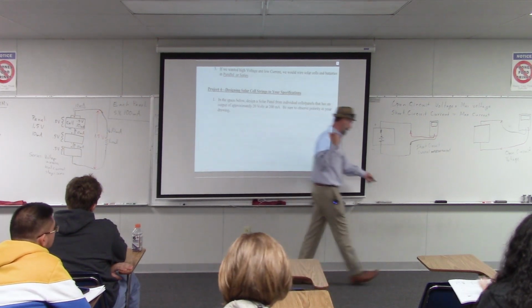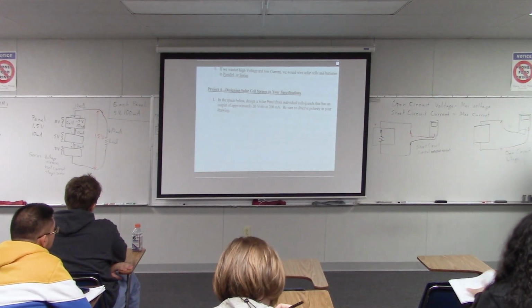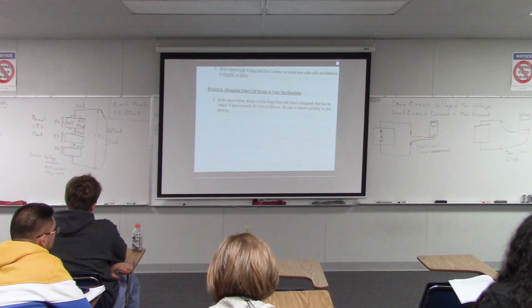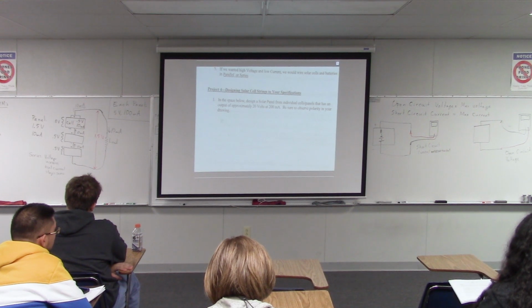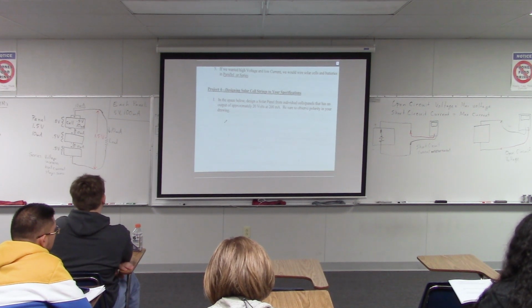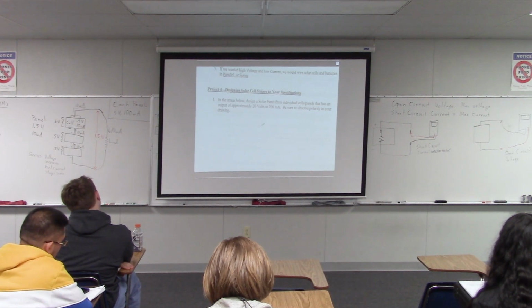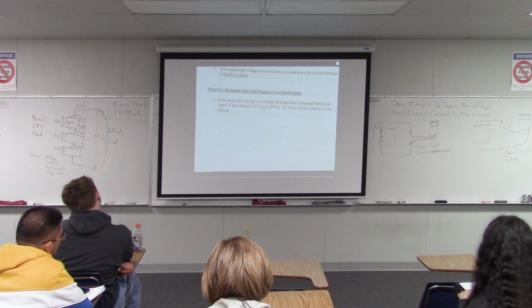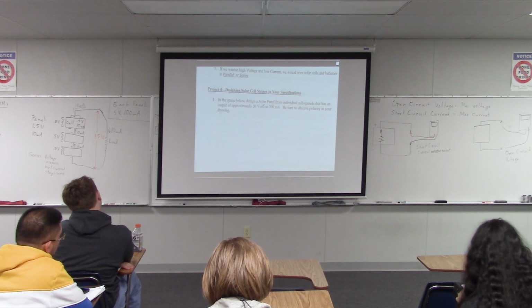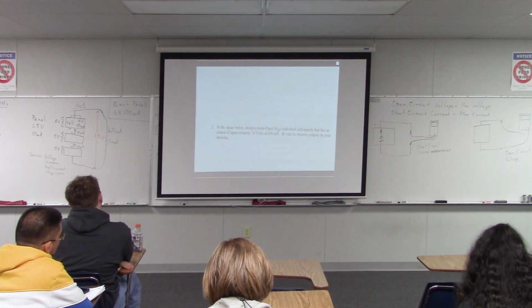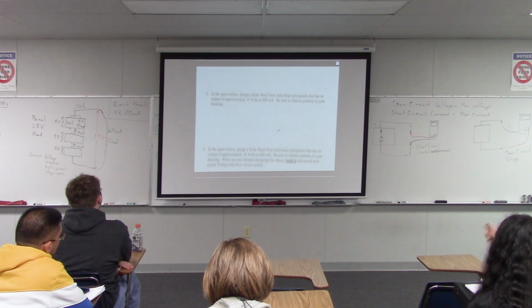And then I'd like you to draw the way that these designs would go, kind of the way that I drew the designs up on the board. So you can draw simplified panels that each have a positive and a negative terminal on it, and then show how you would connect these panels together and how many you would use to produce these different outputs. So the first one would be 20 volts and 200 milliamps. The next one is 10 volts and 800 milliamps, and so on.